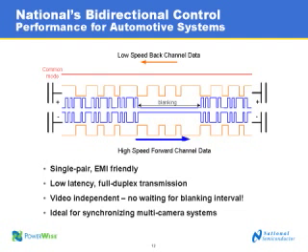Great. And this brings us back to the low latency. The fact that we can send control data at the same time we're sending forward data means that there's a low waiting period. There's no waiting for blanking. We have the I2C data and any of these critical general purpose I/O signals being sent in real time.